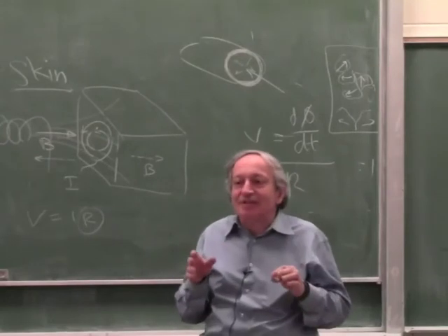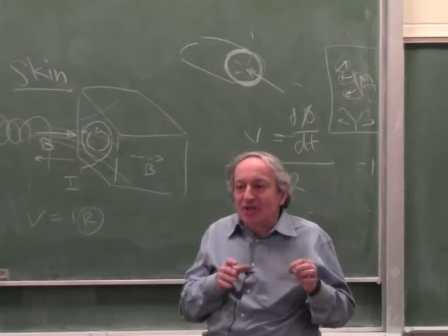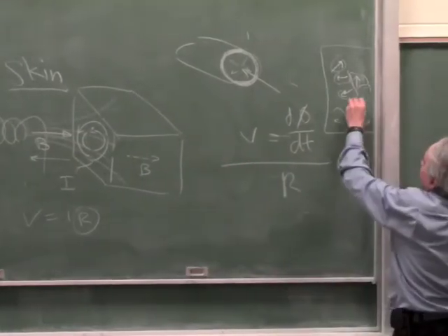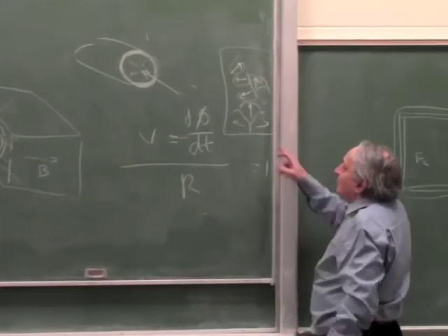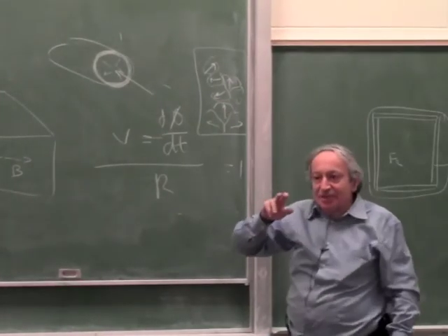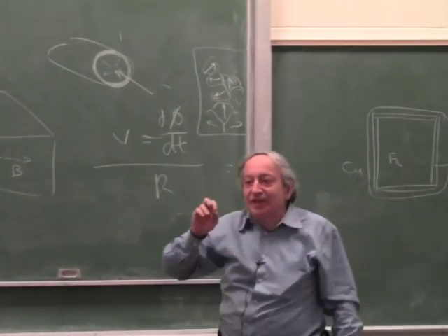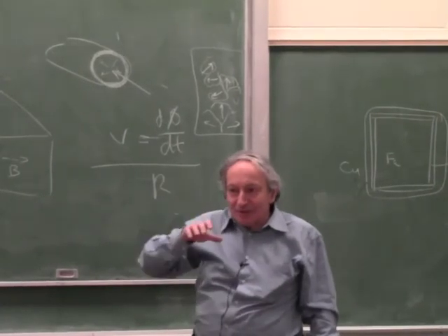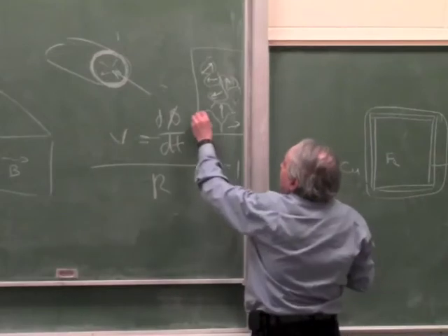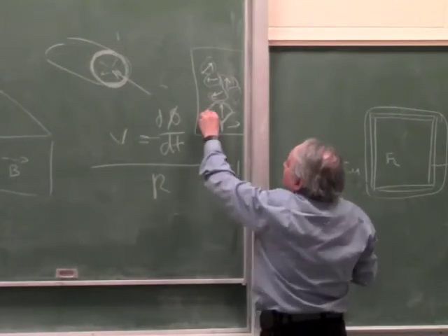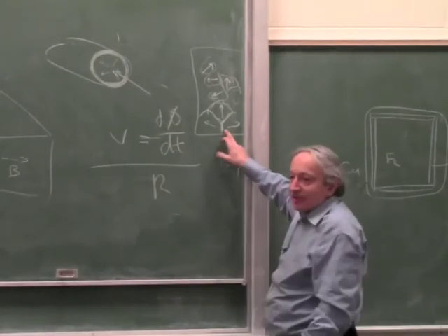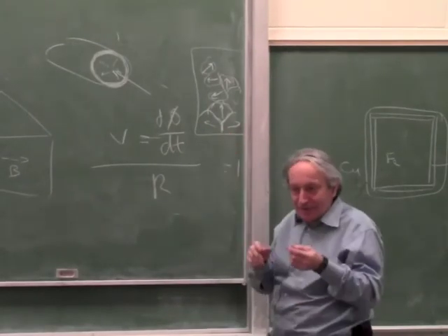The magnetic domains are not the same as crystals. There is some zone which is magnetized this way. It has a boundary, and another zone magnetized this way, but it has visible boundaries. For example, if you take very fine iron powder and sprinkle it on this and look at it under a microscope, you can actually see the boundary, because the same as iron powder will line up between two magnets, it lines up on the domain boundary. So these are actually visible through a microscope.